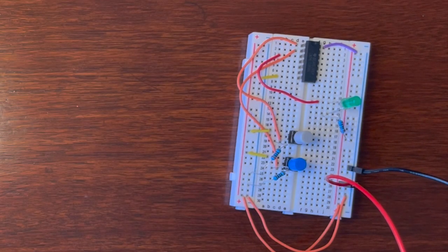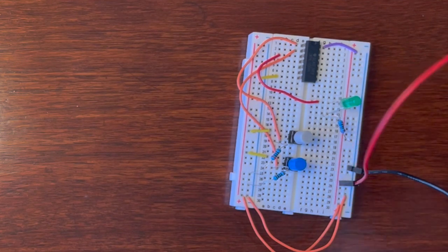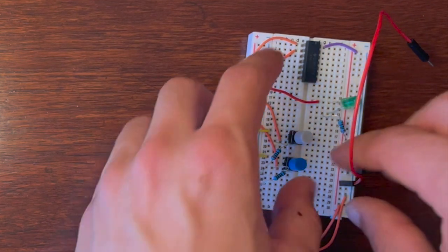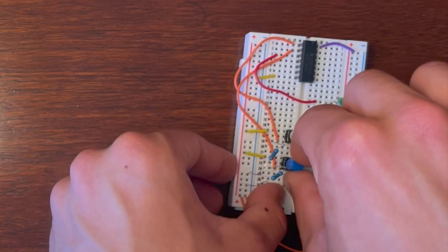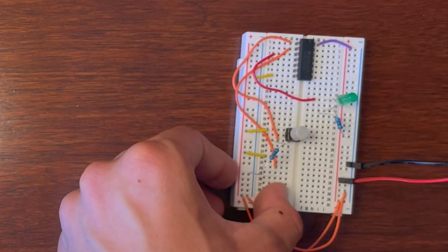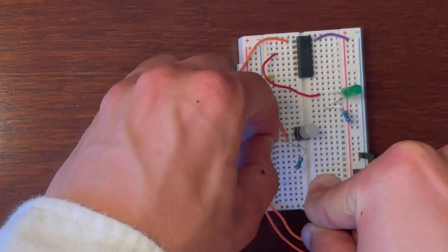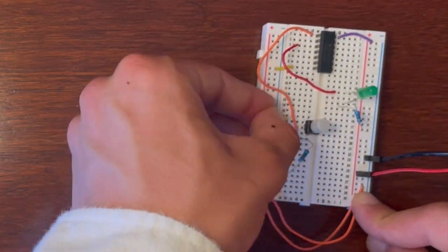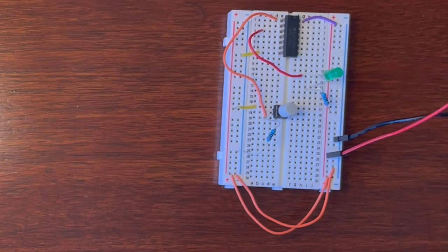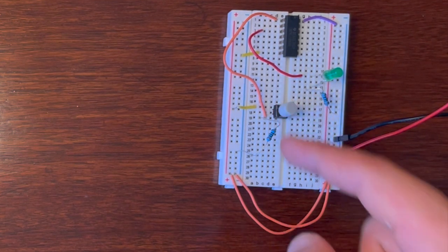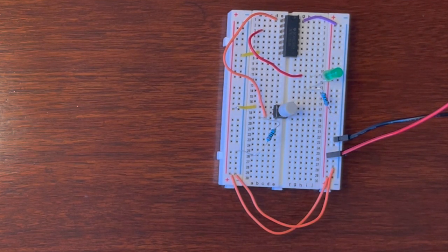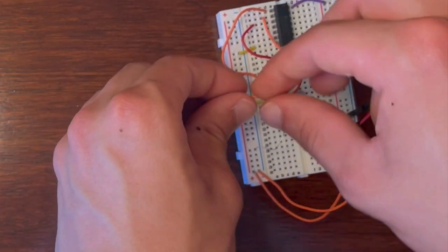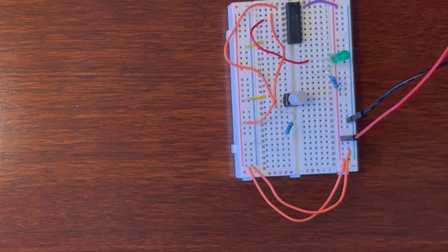Now we're going to try and take our same circuit and build a NOT gate. To do this, we will remove one of our buttons. Now that we've removed the second button, what we want to do is take our input from this button and XOR that with voltage from the positive column. This is like XORing with 1. Now we can test our circuit.